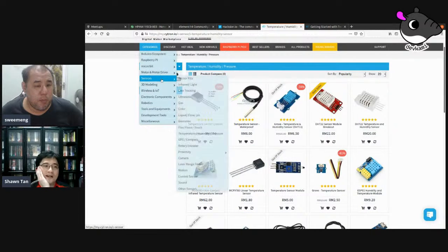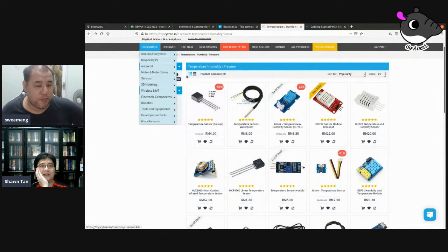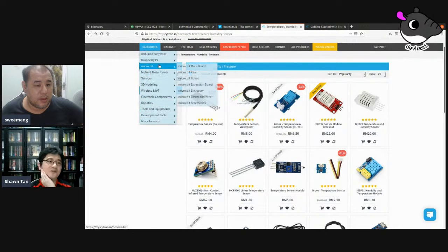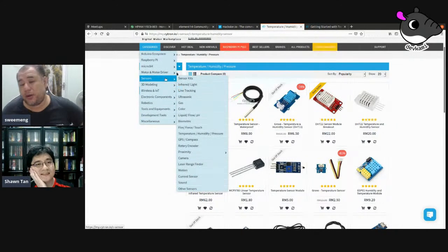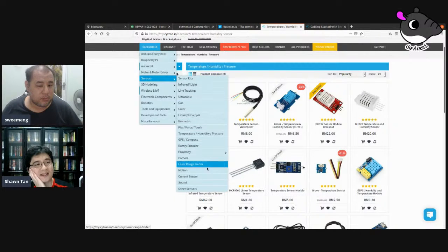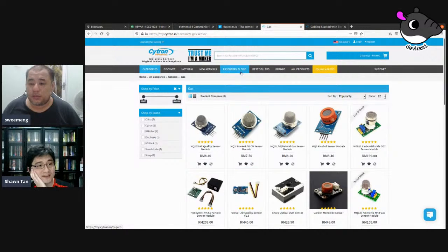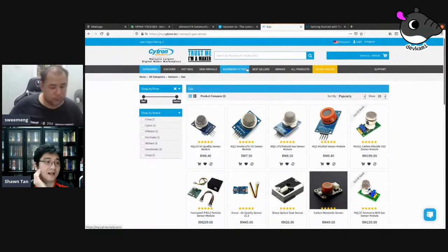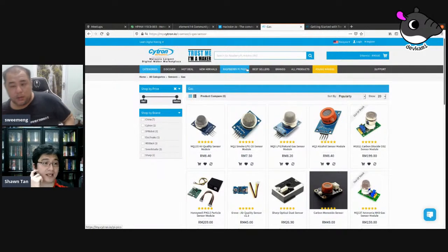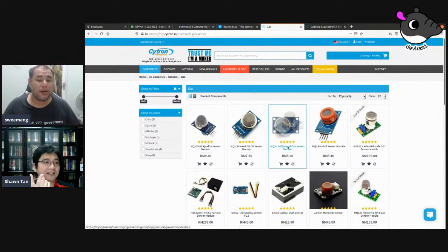The main thing you say is correct: if you are going to build an application, the first question you have to ask yourself is how you want to interface to the sensor. Correct. The interfaces you can more or less divide into certain categories. The analog ones are the most basic, but that will require you to do signal processing on the incoming signal, filtering out noise and things like that. As a result, sometimes people don't need all that. The accuracy of the analog sensor, like for example, you were saying, just a temperature sensor.